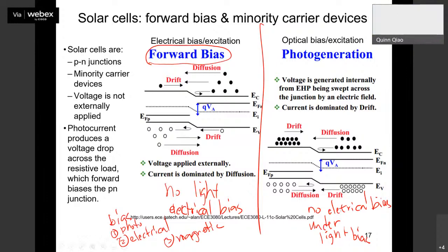Good. So we have one question in the question and answer section, but I guess you have already answered it. He's asking, what are the different parameters to reduce series resistance and increase shunt resistance? I think we answered that question. First, you need to know what device you are dealing with, right? If you are dealing with polymer solar cells, silicon solar cells, or perovskite solar cells, all these parameters will be different. But the common things between them are the interface, the material quality, and the recombination inside the devices, right? So that's basically what you consider, and then the question goes to what device you are working on. Then we can think about what action to take for specific devices to increase shunt resistance and reduce series resistance.